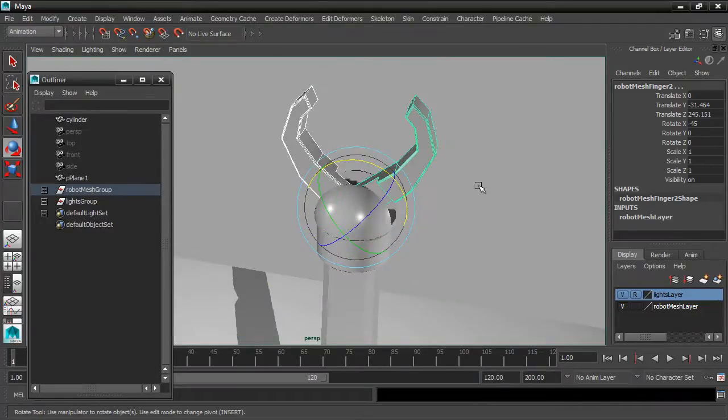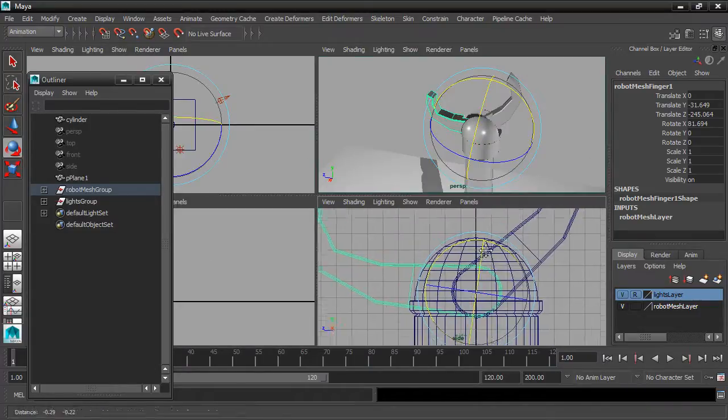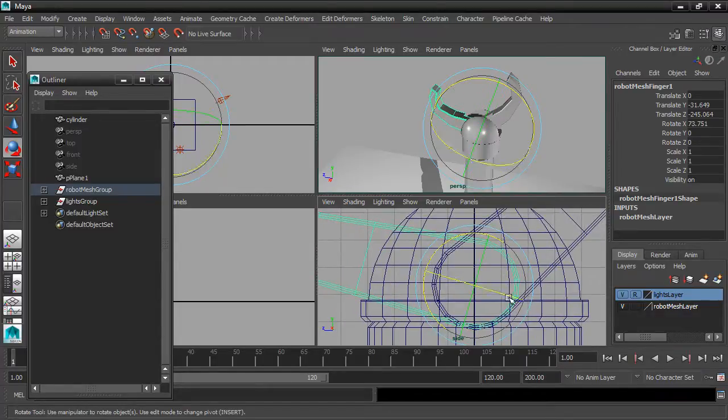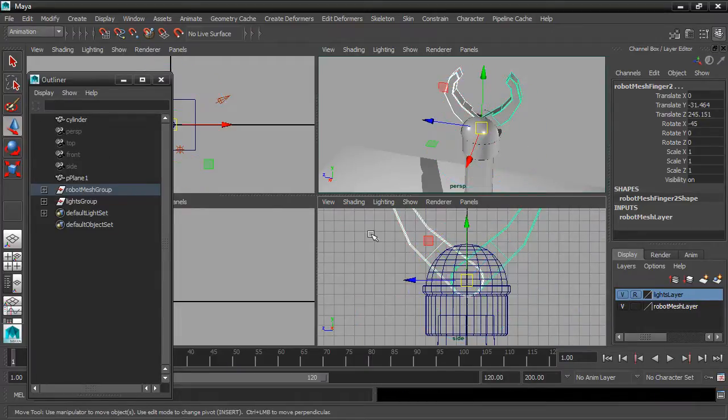And you'll see they're rotating. We can try them individually. At this point, they're fine. Now we want to open them up a bit. We're just going to guess how much that's going to be. Check that in the side view, just so that it's not intersecting with any of the nearby geometry. It looks like it is actually buried inside some geometry here. So, in fact, I'm going to undo those rotations and grab those and move those up a little bit.